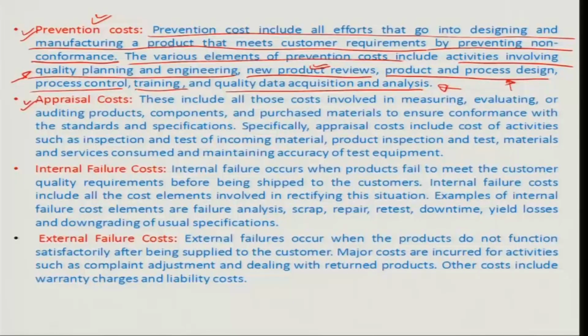For example, the diameter of a shaft may be 1 inch plus minus 0.03 inches. So this is a dimension and a tolerance given in the design itself, and the process should be able to meet these guidelines as it produces. And so how do you know that the process is meeting the guidelines? Obviously is by measuring the output diameter of the shaft which is coming out of, let us say, a CNC lathe, or some kind of a process which produces this turning.